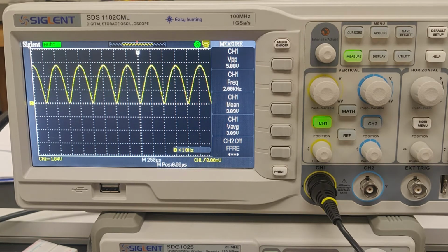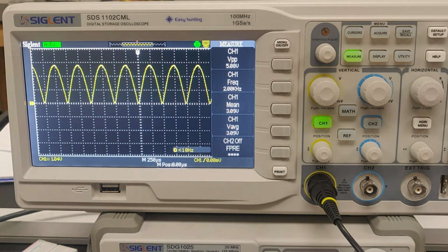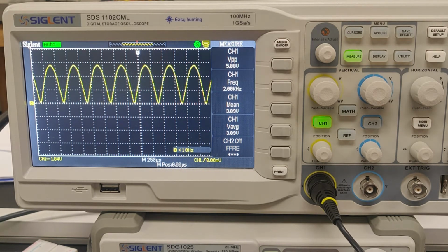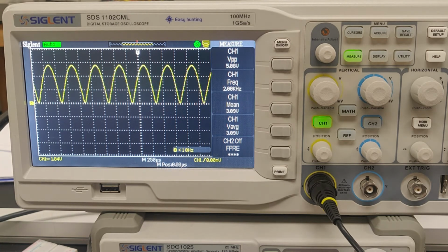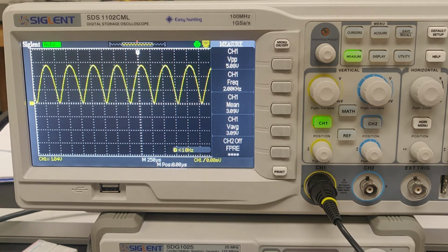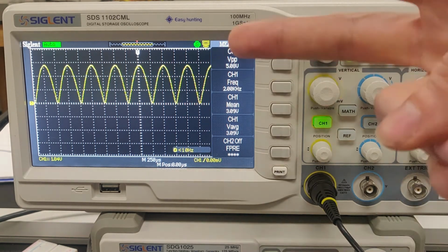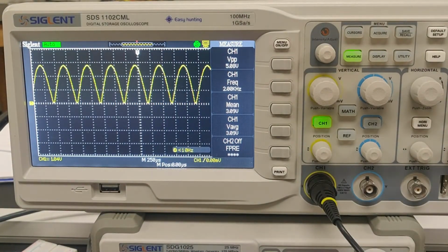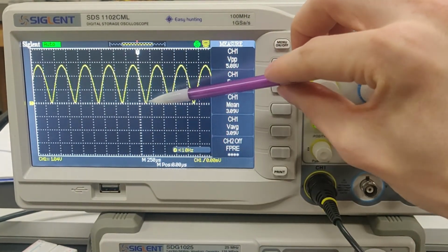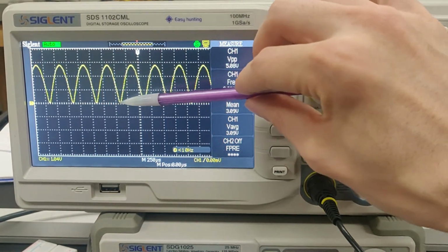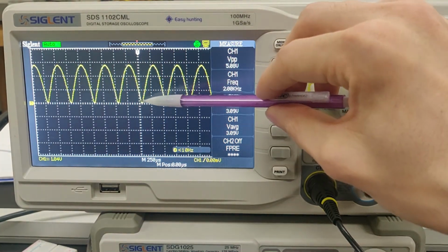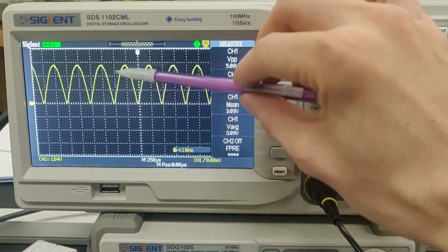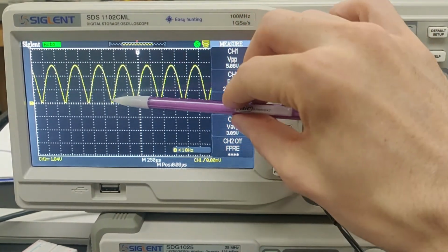And that's because when I was tracing through the circuit beforehand, you saw that no matter if the current is coming out one way or in the other way, the way that the circuit is oriented, it always conspires to return the signal into the same direction. So it flips this negative, but in doing so, if our waveform is no longer down here, then that explains why our peak-to-peak voltage is now half, because we're measuring between here and here. And our frequency has essentially doubled, because a whole waveform originally for our Vin was from here to here, but now one whole cycle is right there.